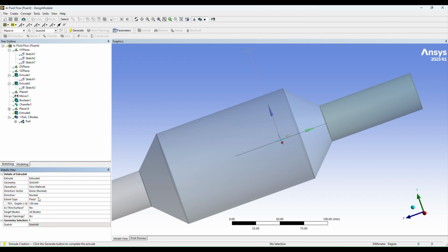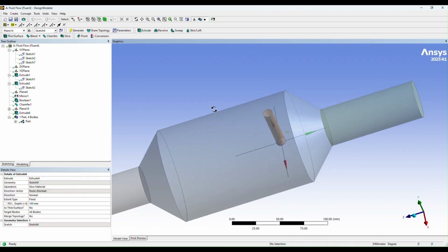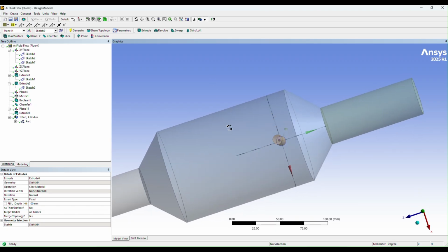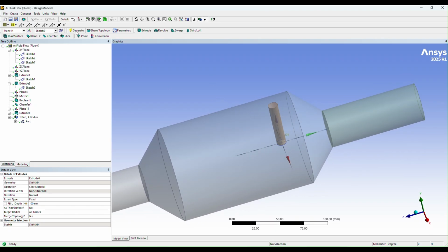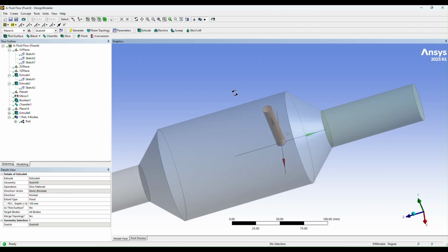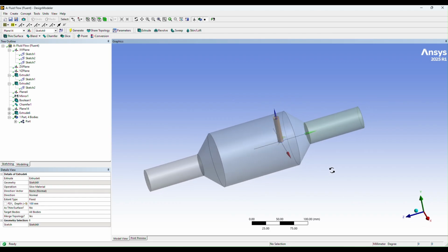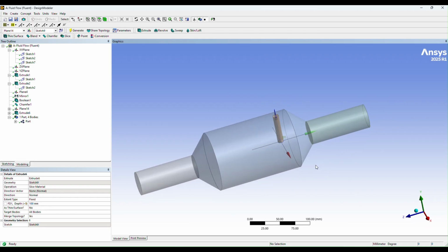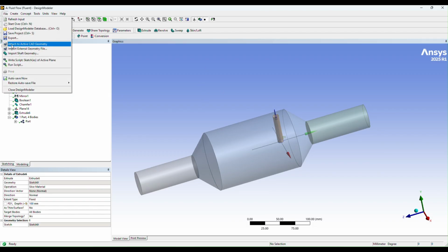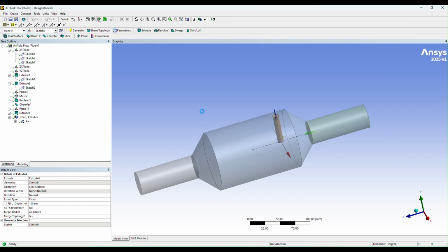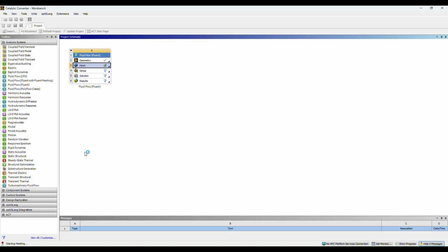Slice the material and then generate. And add the frozen material that was placed in between. Here the sliced material is a little bit different from the regular extrusion cut. So now I'm saving the geometry again. Now going for the mesh.